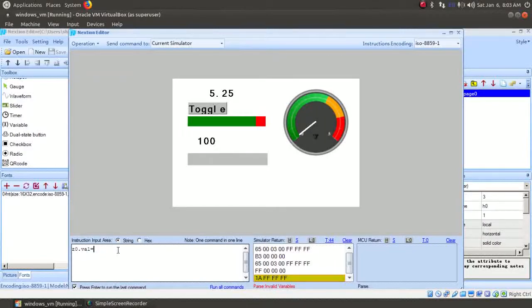If you set it to 0, it means it's at 0-degree angle. If you set it to 90, it will go here. If you set it to, say, around 270, it will go actually here, but we want it to go here. I think it will be around 220 because I've tested this, and since it's moving in clockwise direction, and 0 and 360 are basically the same points, actually if we set it to 322, it rotates all the way to here. So basically you have to calibrate these according to the gauge you designed.